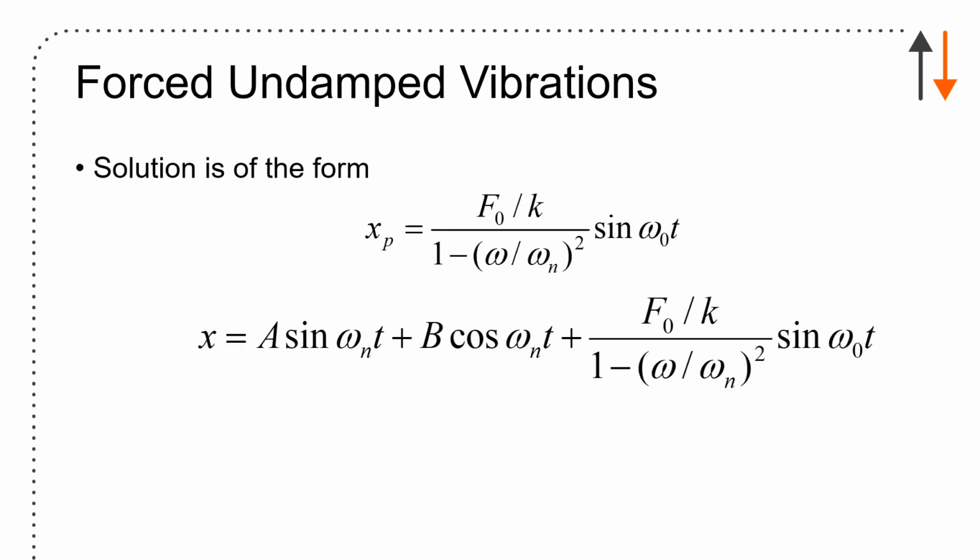That magnification term right here, which I just kind of added in, that particular solution is a bit of a pain in the neck, because suddenly you realize that as you approach the natural frequency, you start to have this thing shake apart. Now, in all likelihood, none of you are familiar with the 1970 Chevy Nova, which had a habit of shaking apart at around 100 kilometers an hour after it had about 20 years of service.